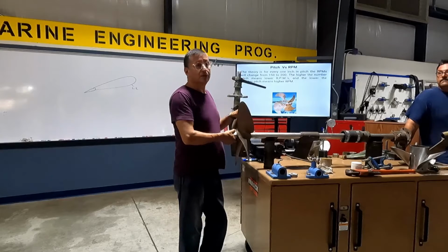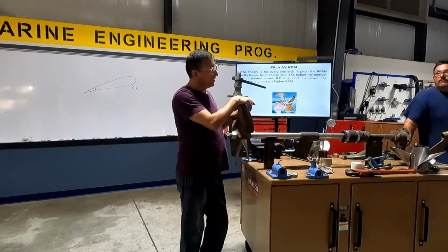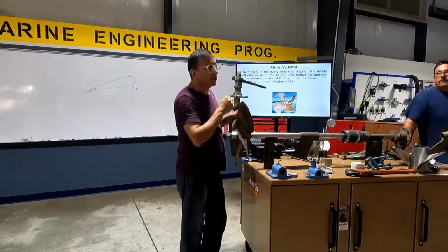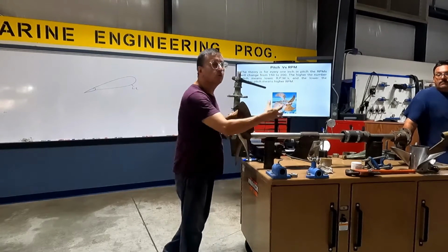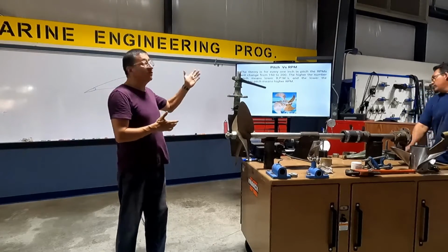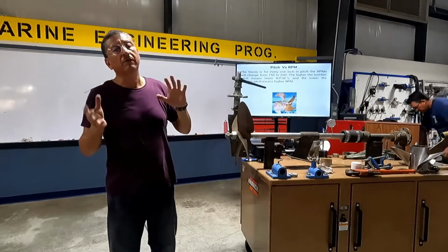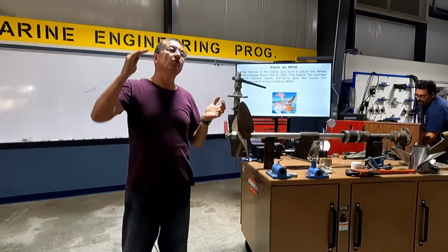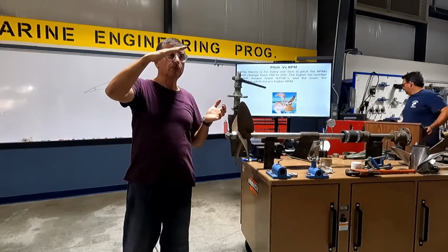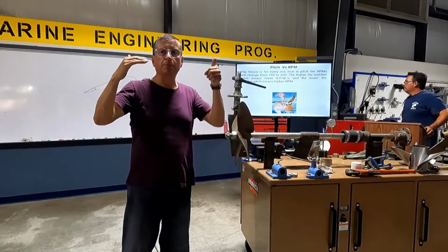Danny, we are going to do that laboratory next week. We are going to replace a propeller in an outboard with Danny and in an inboard with the tool. We have the tool to remove the propeller. Okay. The propeller, don't forget, changes the RPMs by between 150 and 200 RPMs. If you increase the pitch, the RPMs are reduced. If you decrease the pitch, the RPMs go up, okay?